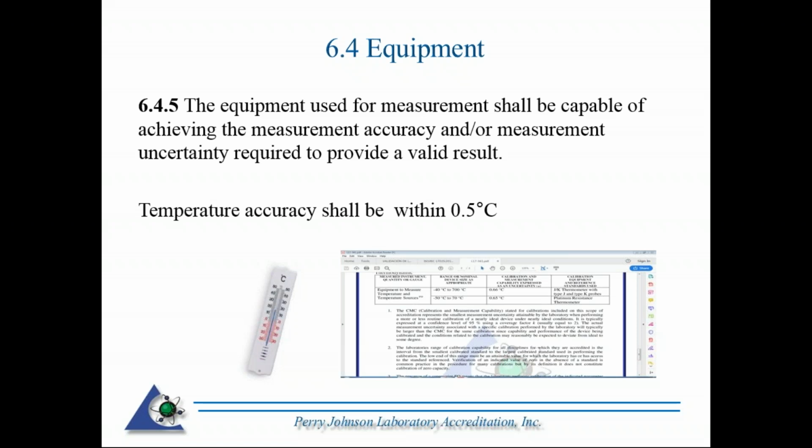Also, what I provided here, I may be going a little bit into contract, for qualification of vendors. If you're also required to have that degree of accuracy, you go to a vendor, a calibration vendor. Always, you may have as a qualifier that yes, they are accredited to do temperature calibrations. One thing you may also want to include is, are they going to be able to provide the required accuracy?